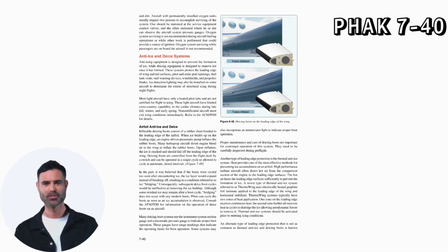Aircraft with permanently installed oxygen tanks usually require 2 persons to accomplish servicing of the system. One should be stationed at the service equipment control valves, and the other stationed where he or she can observe the aircraft system pressure gauges. Oxygen system servicing is not recommended during aircraft fueling operations or while other work is performed that could provide a source of ignition. Oxygen system servicing while passengers are on board the aircraft is not recommended.